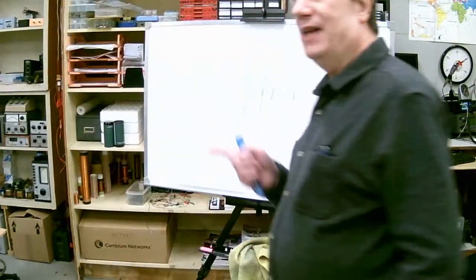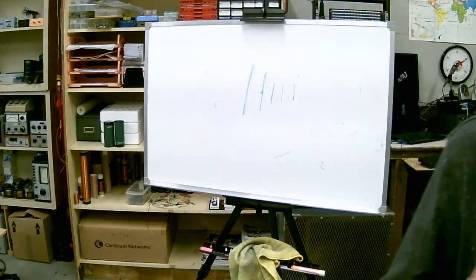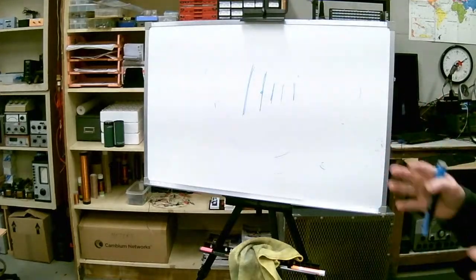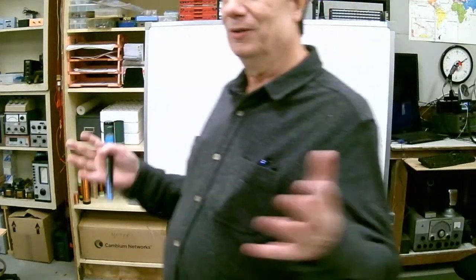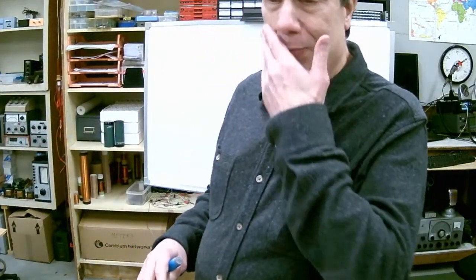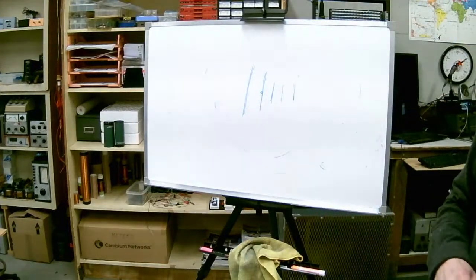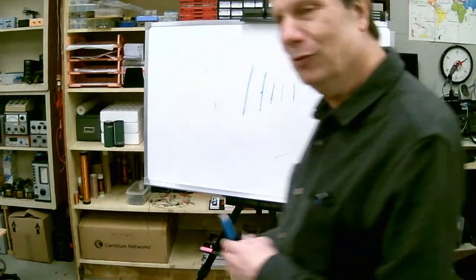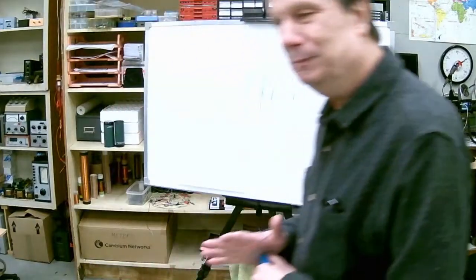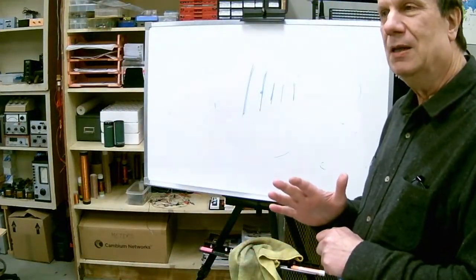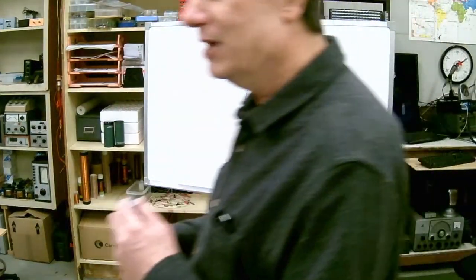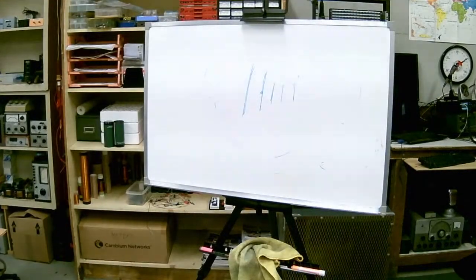A high gain Yagi antenna is designed either for a single frequency or very narrow frequencies. With TVs, you had to cover all the TV channels. So to get any kind of gain at all, you had what's called a log periodic, where all the elements are driven. Now that one there was part of a hybrid. So you say they're all driven, means there's a dipole? That's a driven element, and there's actually a folded dipole.